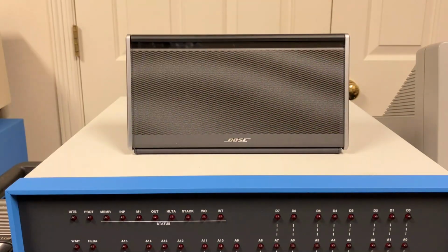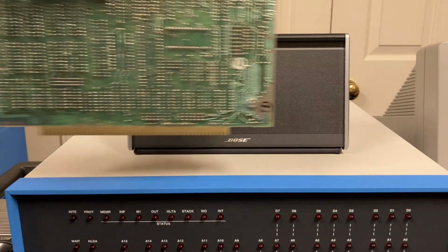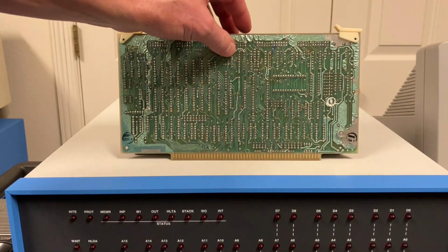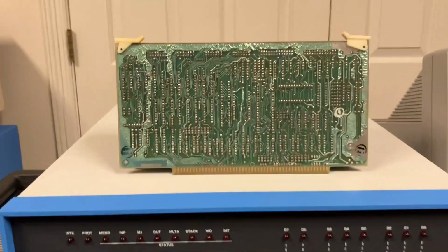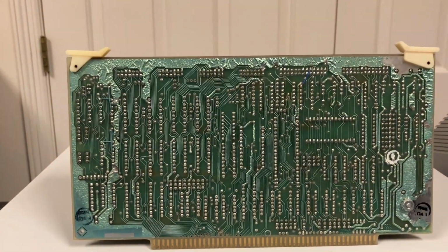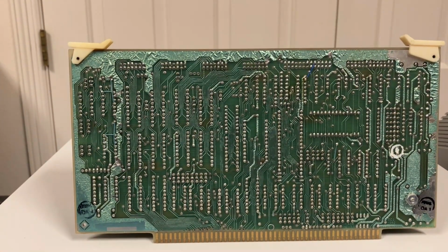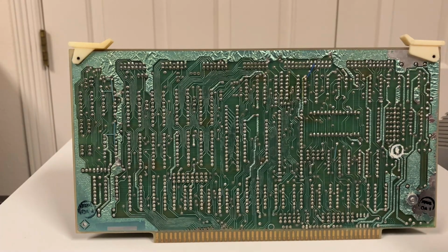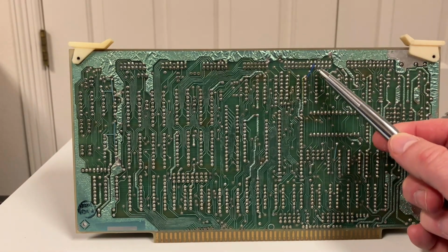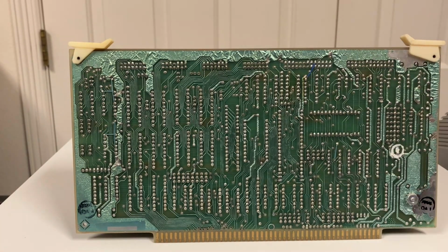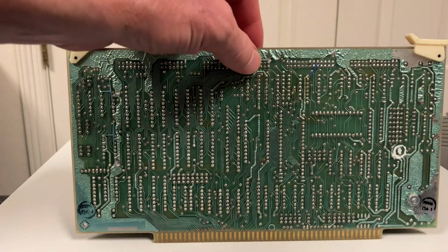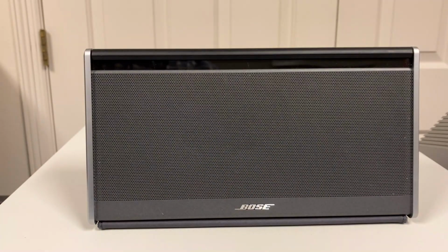Now I do want to have 5 volts on pin 18 of the DB25, and as you would expect, this board does not happen to do that for us because that's not like a standard of any sort. So if you look real carefully, you can see I put a little jumper wire on here. That's this little blue wire right there. I don't know if you can see it. That's going from 5 volts, and it's putting it on an IDC pin that'll end up on the DB25 pin 18. So there's my 5 volts on there.